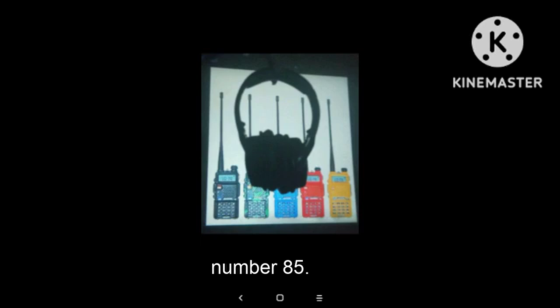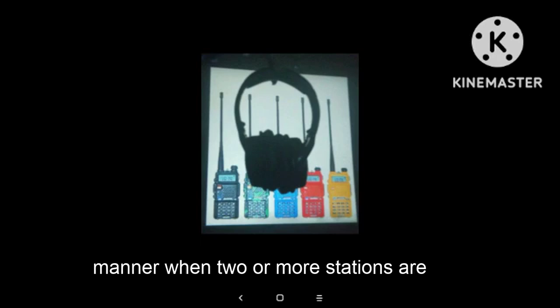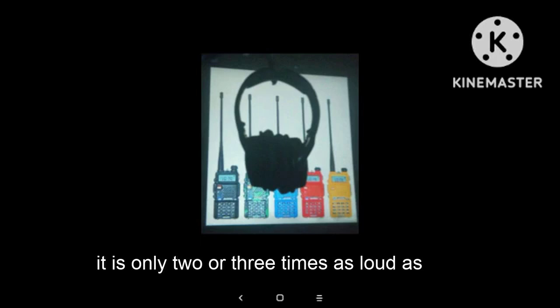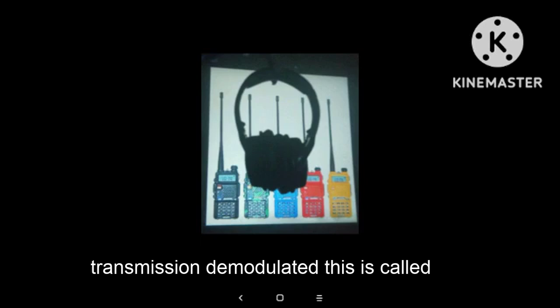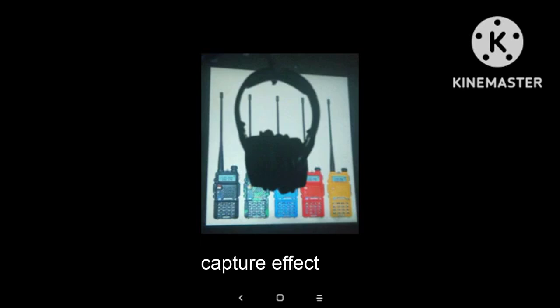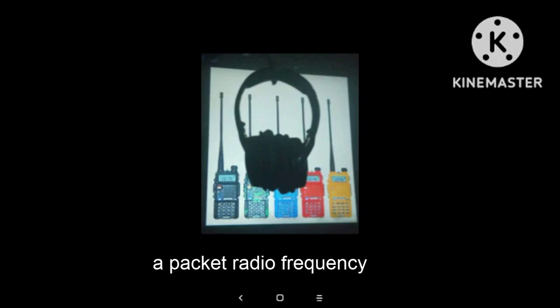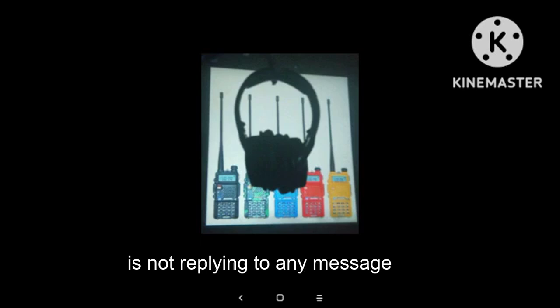Number 85. FM receivers perform in an unusual manner when 2 or more stations are present. The loudest signal, even though it is only 2 or 3 times as loud as the other signals, will be the only transmission demodulated. This is called capture effect. Number 86. What does monitoring mean on a packet radio frequency? A receiving station is displaying messages that may not be sent to it and is not replying to any message.